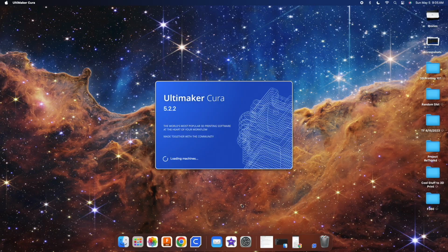So as we talked about, your 3D printer reads files in G code. G code is made by the slicer, and it controls everything about your printer while it's printing. It controls the temperature, it controls the movement, the extrusion, everything. If your slicer is not properly set up, it's going to be much harder for you to achieve good looking prints and good functioning prints. So without further ado, let's get started.